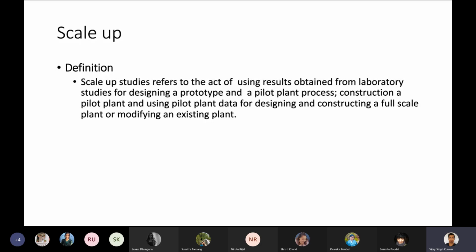If you gather just a very few, 5 or 10, water molecules, they don't have those kinds of properties. Similarly, when you work in 1 liter versus 1000 liters, there are many properties that are not observed when you are conducting studies in the lesser volume. For example, at small scale the carbon dioxide generated will not increase the temperature of the vessel, because the volume is small and the surface area is large, so there is never a problem of heat exchange. But at large scale, when you are generating more, there is this problem of heat generation.